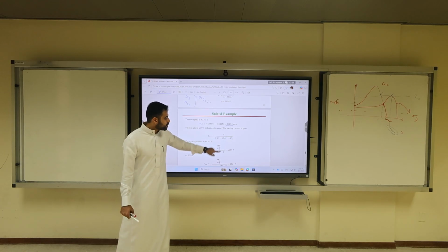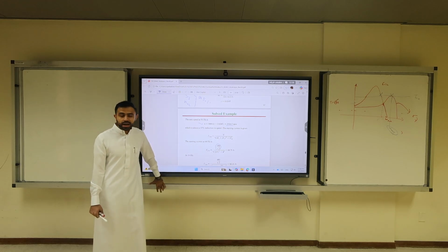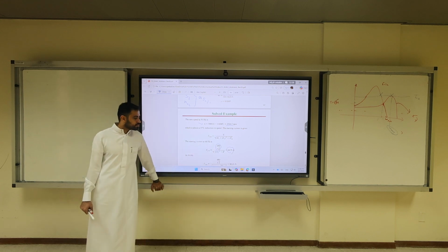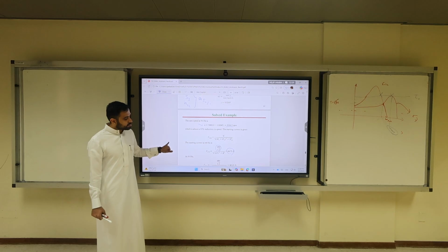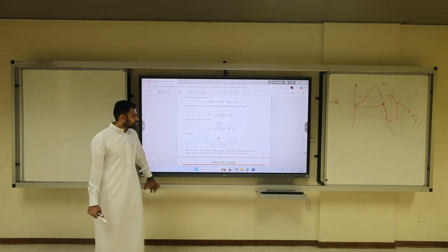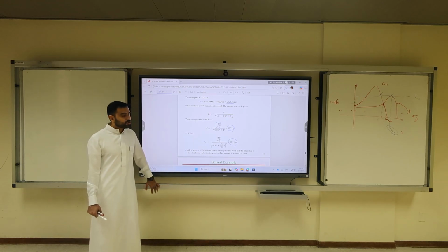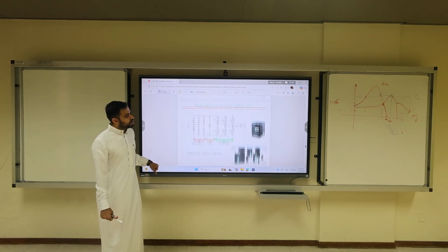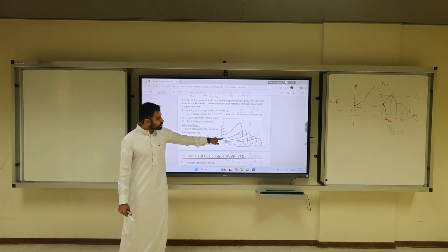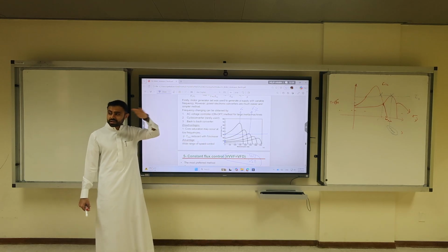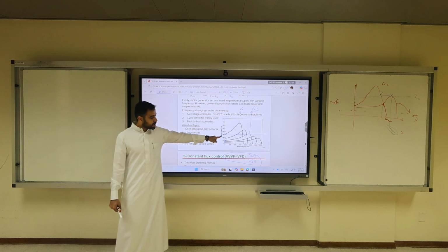Again, here use V1. This is phase, not line to line. Okay, I'll try to fix the slides. So this is 68.75. Is that 60? What was it? This is at 60 Hertz. What's the starting torque at 50 Hertz? It's 82. So starting torque is higher. Look at the curve. If you increase the frequency, starting torque will be higher and starting current will be higher. So that's why we need to use V over F to keep starting current constant. Yeah, starting current is higher.